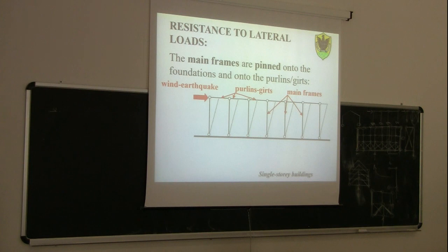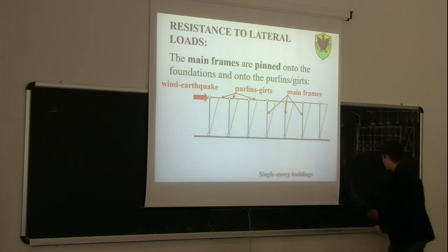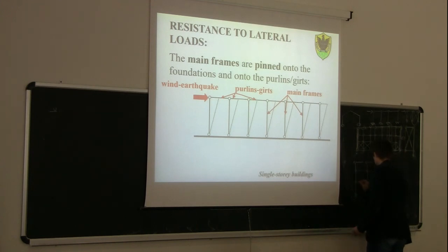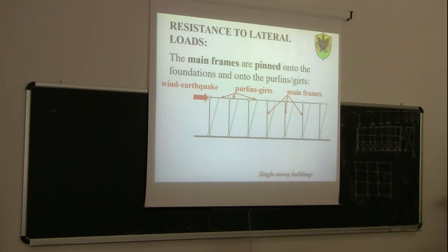Okay, is it enough to put a vertical frame to make the system stable? Now we go back to what we were discussing before. This is our case. Purlin. And for example, we decide to make a cross here, a vertical cross. So we have a vertical cross like this, a bracing system here and here. Okay? Is the system now stable? The roof. What's the problem with the roof? The roof is not stable. We have to put some bracing also in the roof.